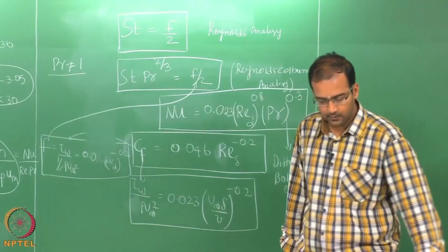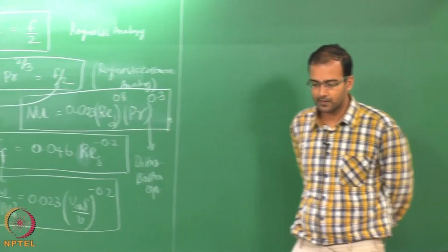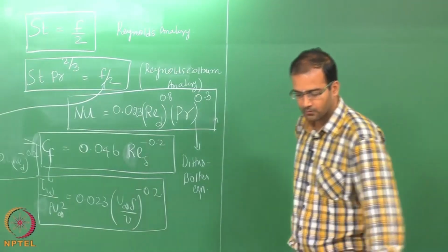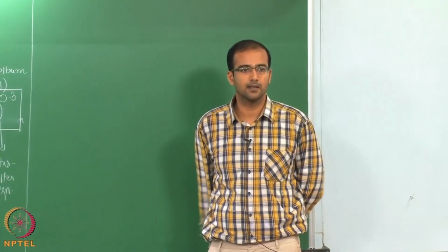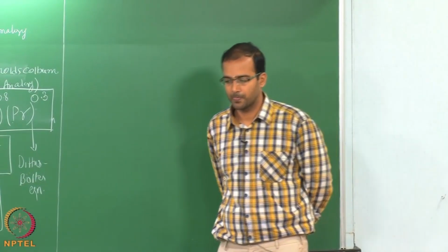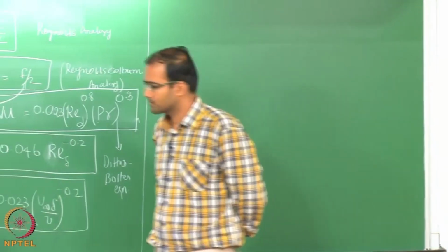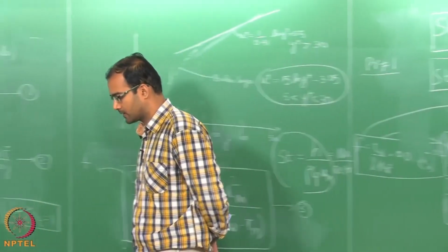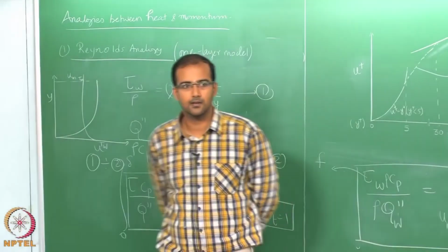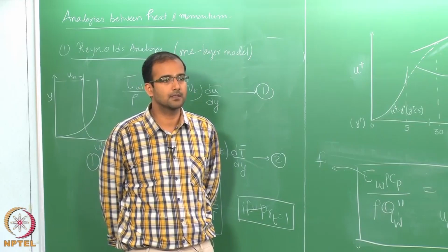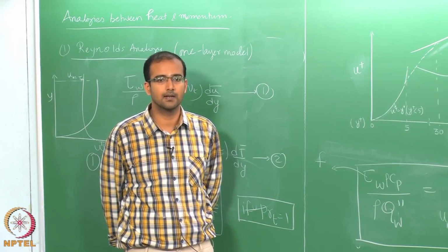So for the internal flow case, it is a very straightforward thing, whereas for the external flow you have to use the momentum integral, solve it, then use the Reynolds-Colburn analogy. Although turbulent flows are considered theoretically very complex, very reasonable simplifications like these have yielded useful results.